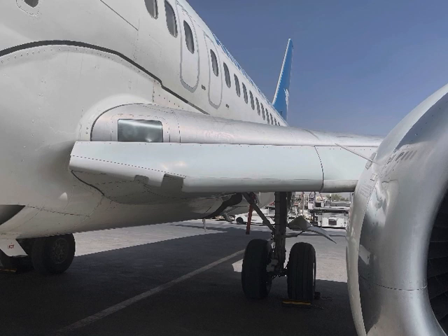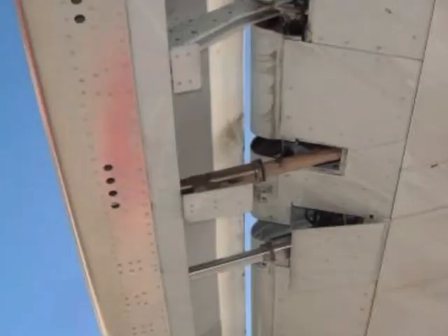Generally, in the leading edge of the wing, the movable surfaces attached are the leading edge flaps and leading edge slats. Mainly we have two leading edge flaps in the leading edge of the wing, inboard of the engine towards the fuselage where the wing is thick, and then we have three panels of the leading edge slats outboard of the engine towards the tip of the wing where the wing is thin.